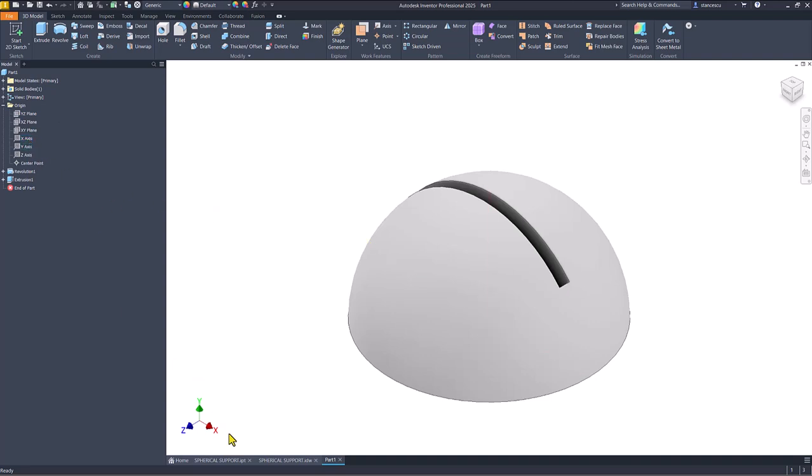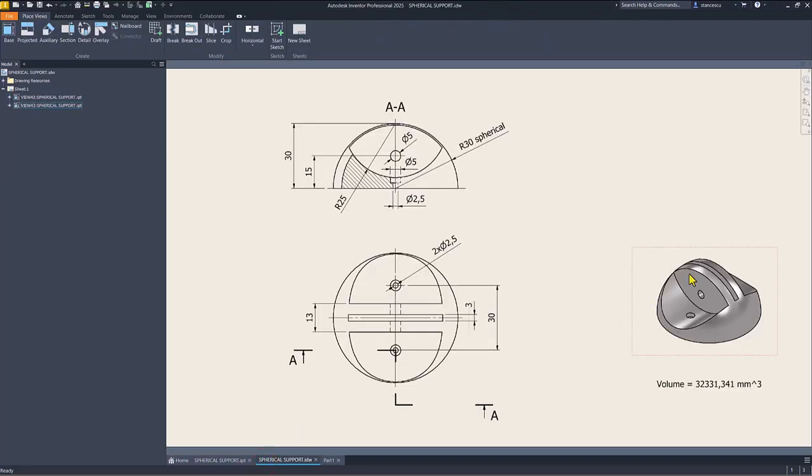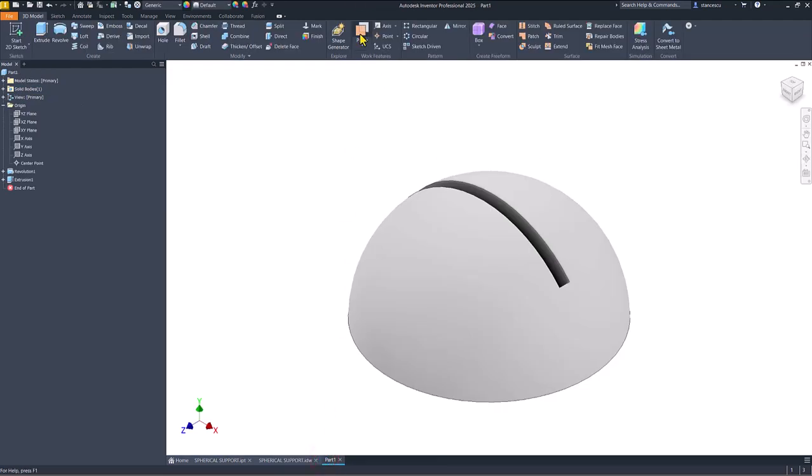Another feature is this cut. The distance between these two faces is 13, but we use half of this dimension so that we create a new plane based on the XY plane and at a distance of 13 divided by 2.